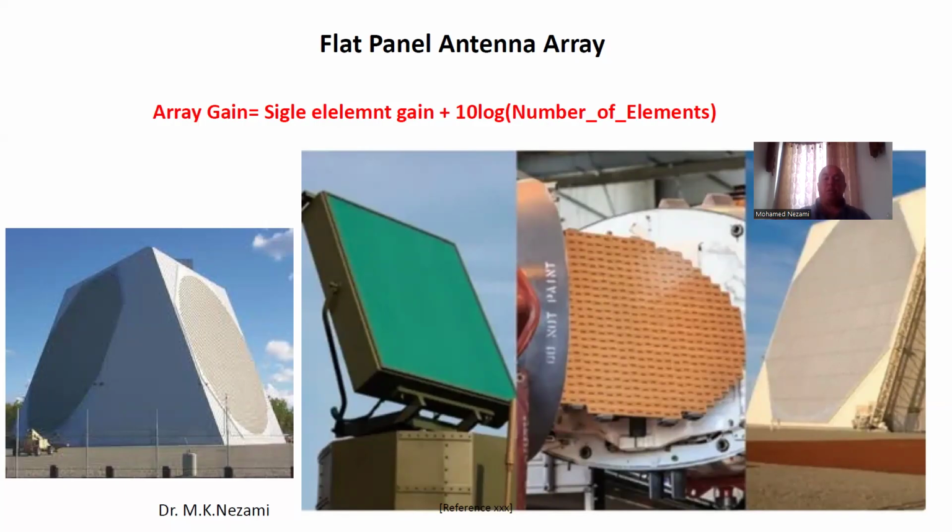That's a hefty amount of work. It's a very important stage of any radio design, and if you really examine it, it turns out it's probably more complicated than the antenna array itself. Because the antenna aperture design engineers assume here is the vector of weights or values of amplitude, distributed values, tapered or uniform on the elements, and they just site the elements with that, and then they work with that.